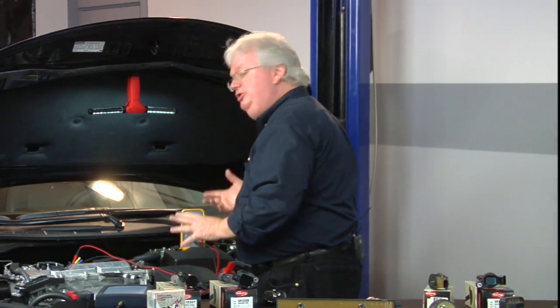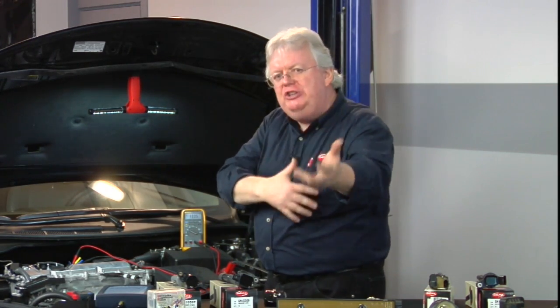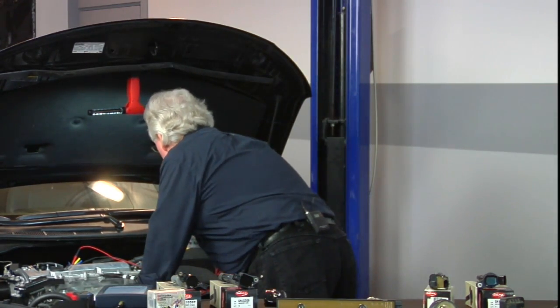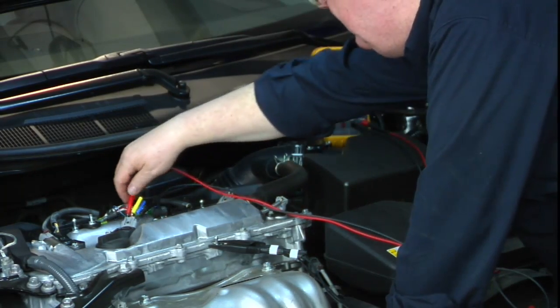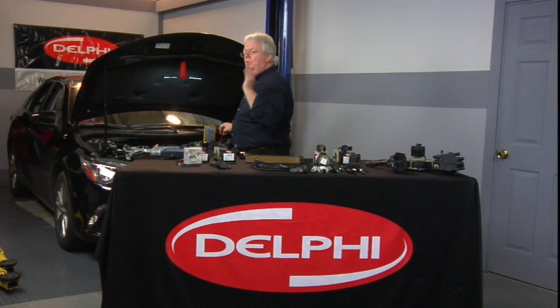We've established good power and good ground. Now let's just see what we can see in regard to resistances of the actual module. Now this is going to be some things that aren't going to necessarily be in the manual, but just if you're curious to see what's going on, we'll turn it to ohms now. And we'll go between ground. If we can have the key turned off, because we don't want a live car here.